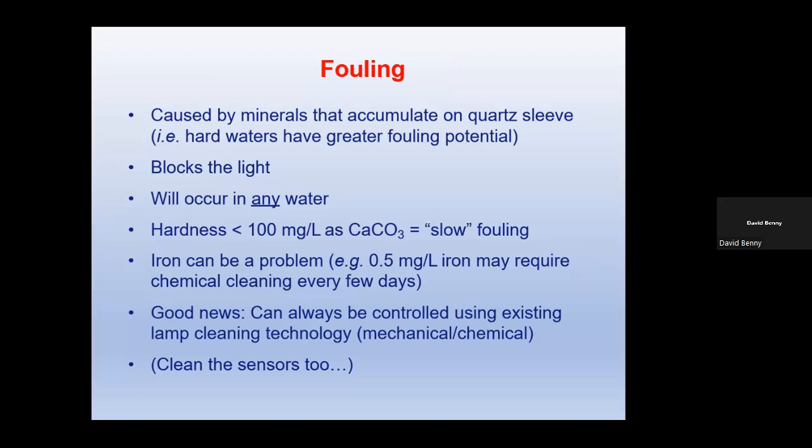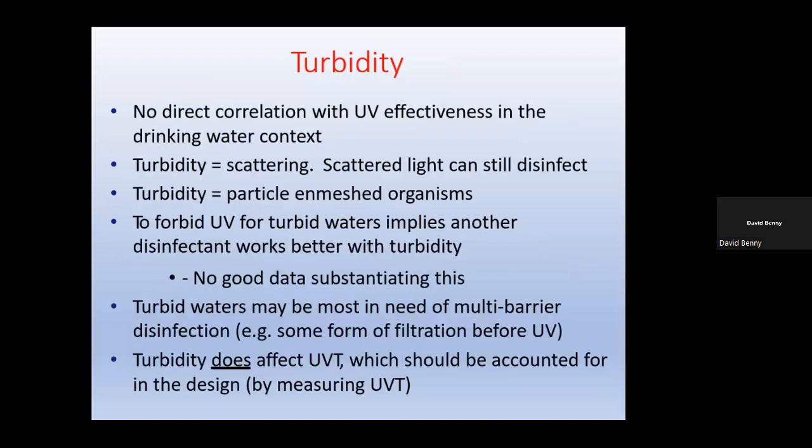Fouling. What can it be a problem? We have the same problem with turbidity. So traditionally, I would have advised people here in Trinidad, where we have lagoons, whether waste stabilization ponds or aerated lagoons, that UV should not be used because you have a lot of microscopic algae that causes the UV to be ineffective.